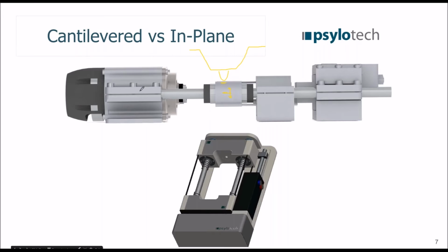To combat that, we've designed this load frame all along an axis here. You can see the actuator, the crosshead, the displacement sensor, the load cell, and all the support structures along the same plane. Now we contrast this to our first design here, where you can see we weren't so knowledgeable about the optics and the issues that can come up. A lot of the designs of other competitive frames that are out there use a motor that's attached to some sort of a gearbox and dual lead screws, dual opposing lead screws.